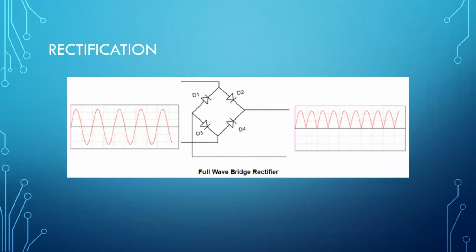Rectification is the process of removing the negative parts of the AC voltage to make a partial DC voltage. Since AC voltage is defined by a sinusoidal function, the voltage oscillates between a maximum and minimum voltage, which are equal and opposite values. This process of rectification can be done with 4 diodes arranged into a bridge.